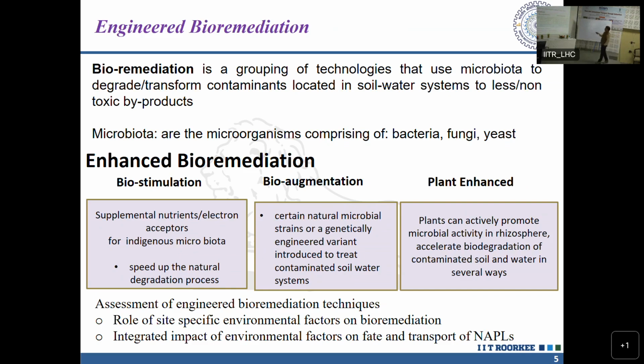The second technology is bioaugmentation, in which we generally develop new strains of the microorganisms, or in simple words, we go to the lab, we go to the market, buy the microorganisms, and go to a polluted site and insert those additional bacteria to that site. So there are already bacteria available at the polluted site, and we also introduce the new strain. So the number of the bacteria which are going to be responsible for degrading these contaminants is going to increase. If the number of the bacteria is going to be more, indeed the time needed for removal of the contaminants is going to be less.